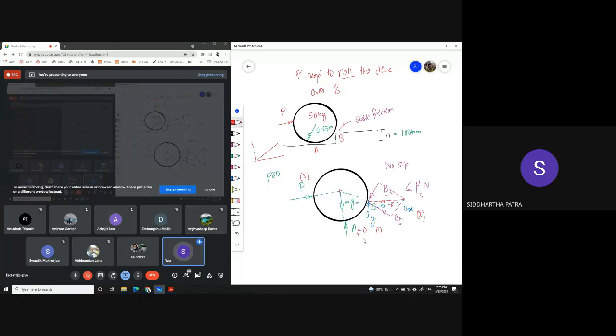Since I'm calling B a frictional support, you might be confused and be thinking that A might also be a frictional support, which could be true. But the point is, the lifting effect only starts when you no longer need the support of A. That means whether it's the normal or the tangential component of the force at A, that simply has become zero. So there is no unknown from A. So we are still getting an unknown count of 3, and you have 3 equations to solve them from.